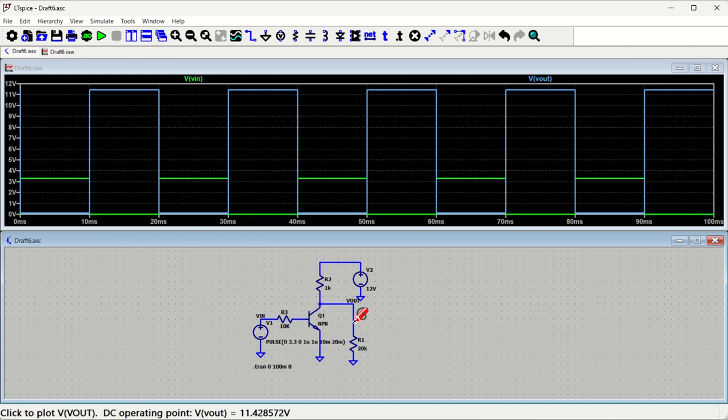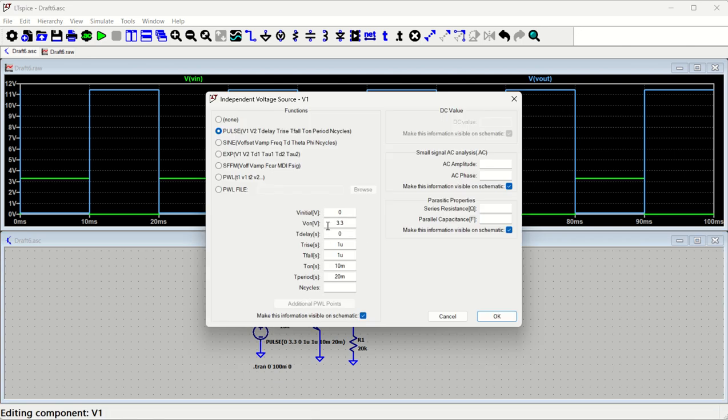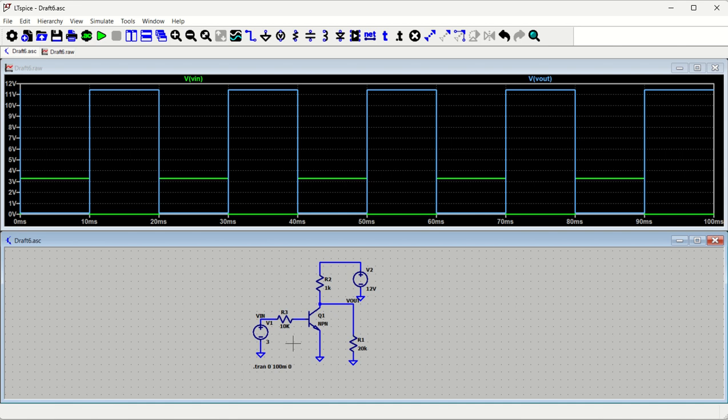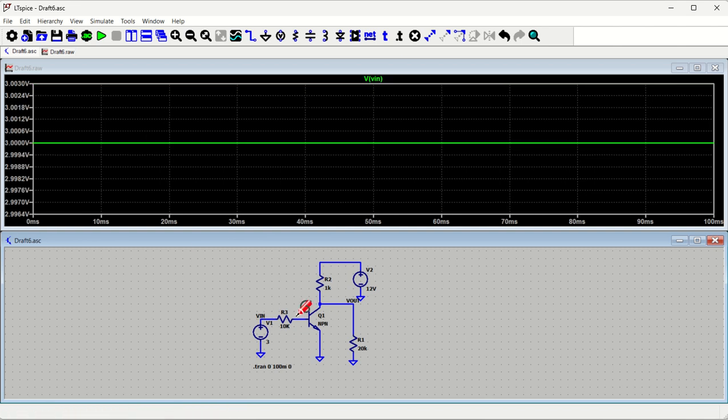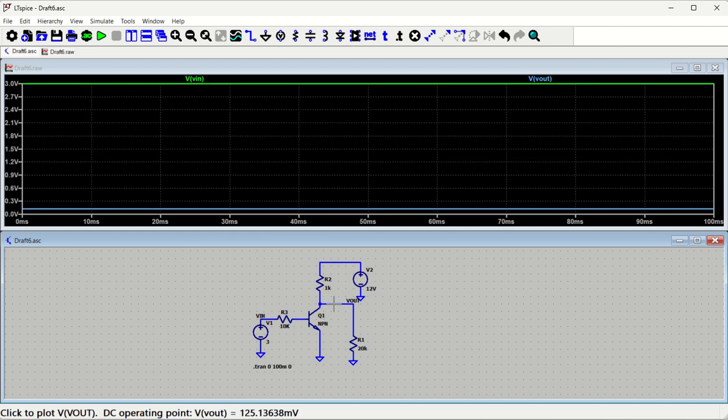So the transistor as a switch, we need to have this particular understanding, and we can apply this. If you know the transistor characteristics and if you know everything, then you can put a current source also here, and that's how you can place this. Let us say we always want to make it on, then we can simply right click it and put a voltage source of, let us say, 3 volt, and it will become a 3 volt source, and this will be always on. So you can see my voltage at this input terminal is 3 volt, my voltage at output terminal will be what, 0, because it is always on.